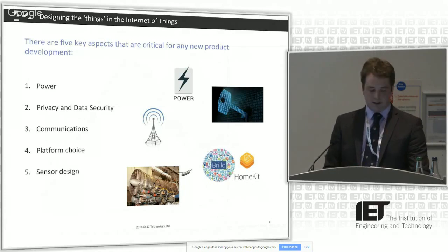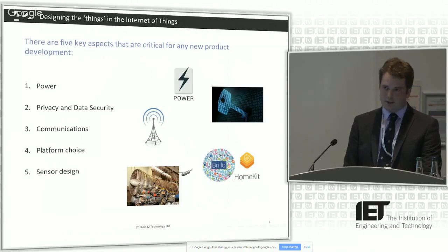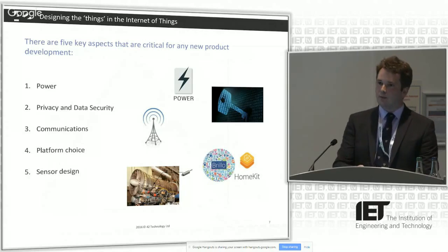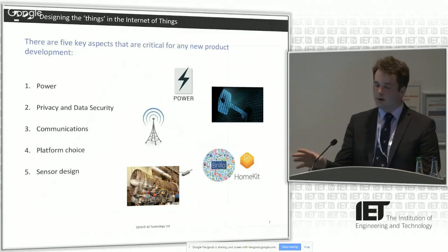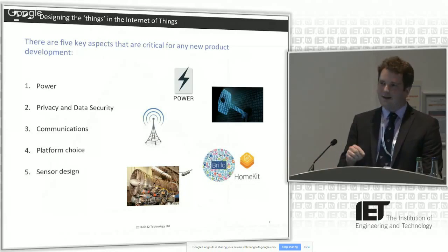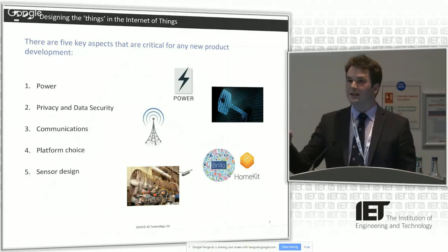So today's wireless devices can be made to run for years on a single battery through the use of low-powered sleep between tasks. So you want to have sensors on board which are able to sense what's going on with it, put it to sleep when it's not being used, wake it up when it is being used.